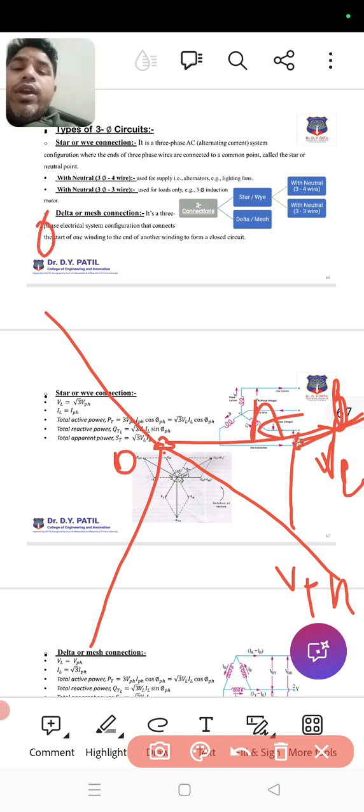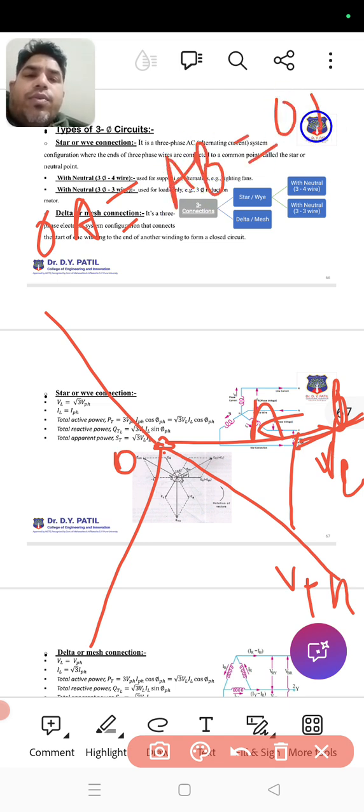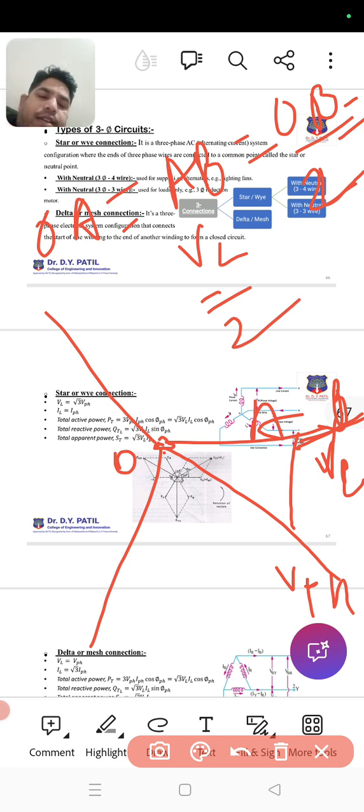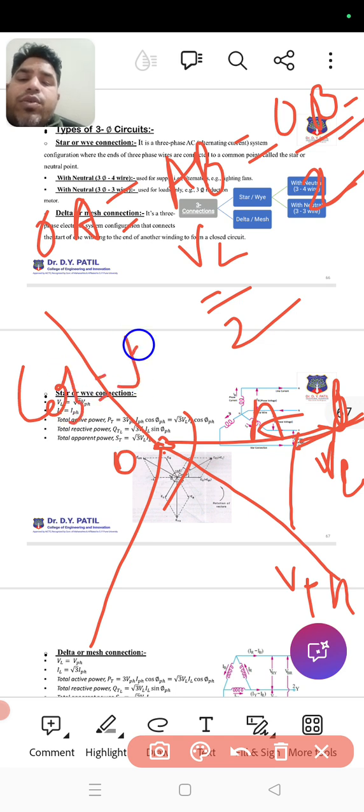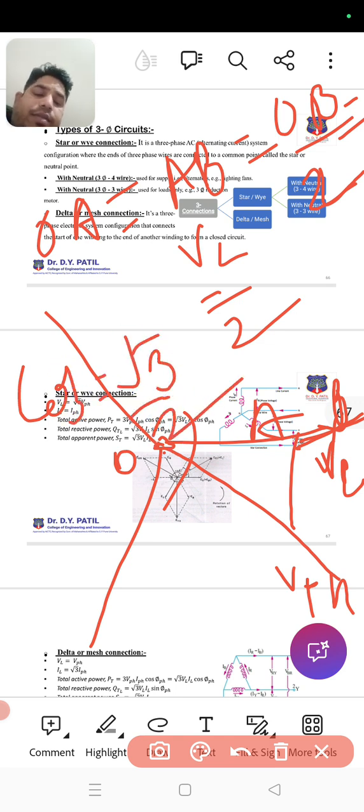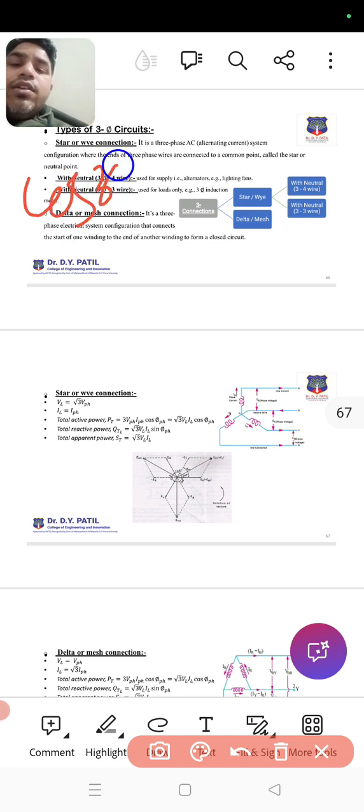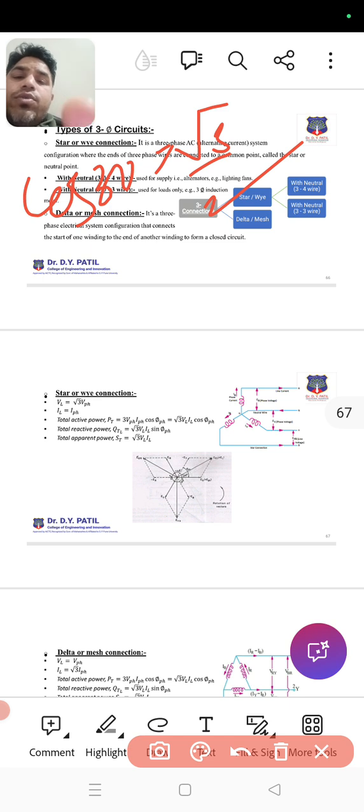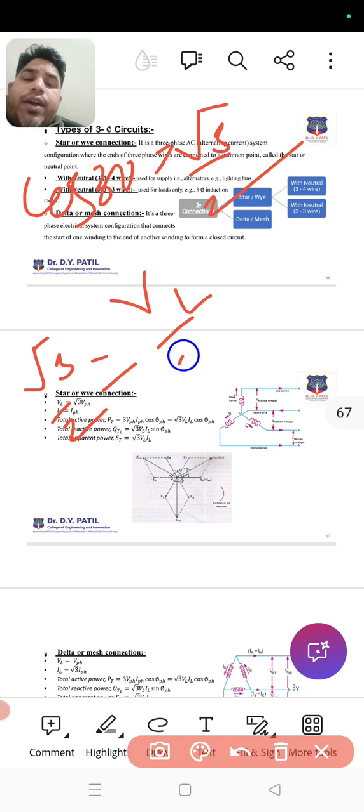So we know that OA is equal to AB. So OB is equal to 2, or VL divided by 2. Is this correct? Okay, so it is a 30 degree angle. The cos 30 is always equal to root 3 divided by 2. Correct? So root 3 divided by 2 is equal to VL divided by 2 over VPH.